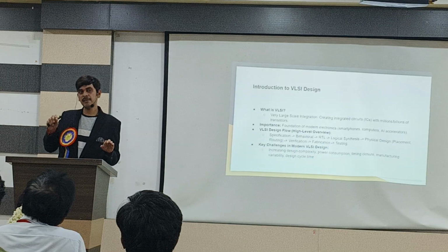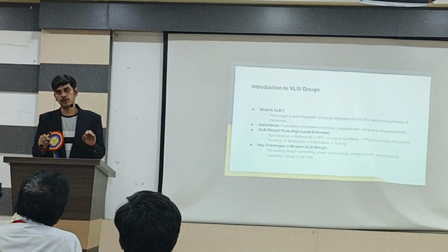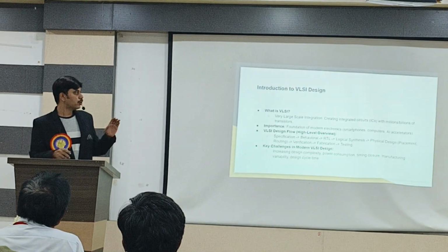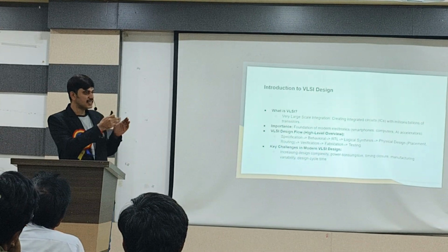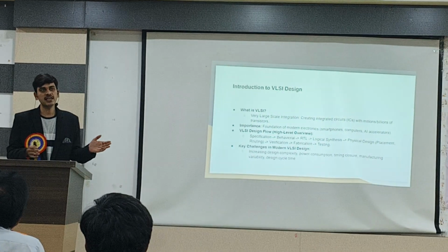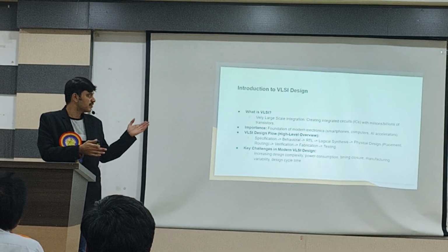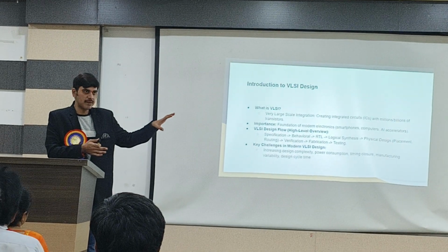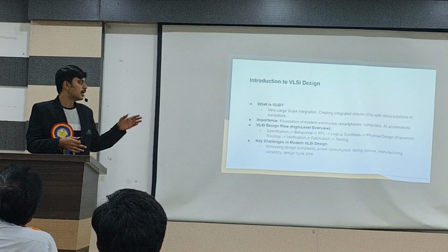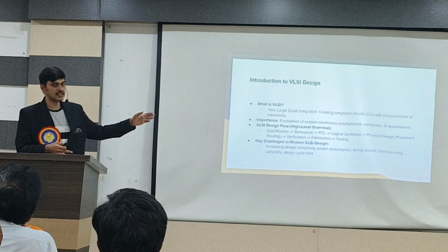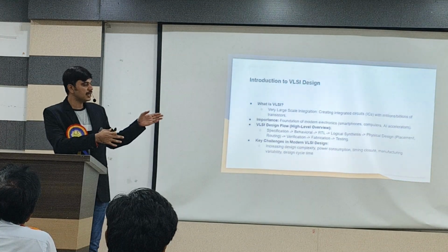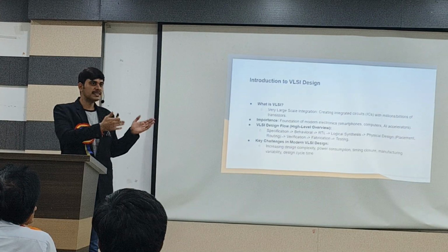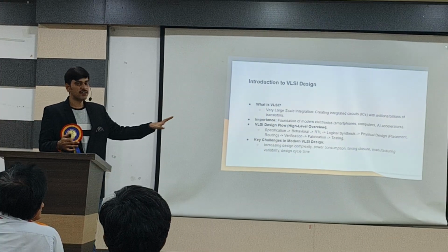These timing checks have to be done very carefully, before the final check. So this comes to the physical design team, where there are two things: physical implementation and physical design. Physical implementation comes under synthesis and timing, which I worked on: pre-layout and post-layout STA and synthesis. These things are done in STA and PD implementation. In PD, I do placement, CTS, and routing. These are the next further steps.